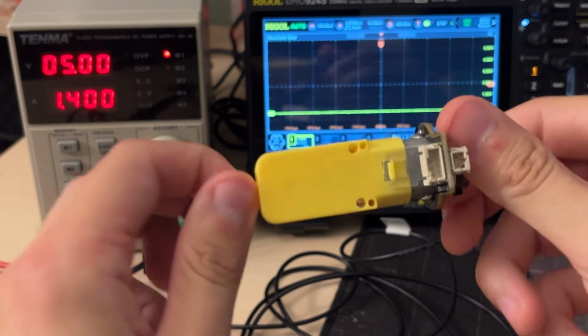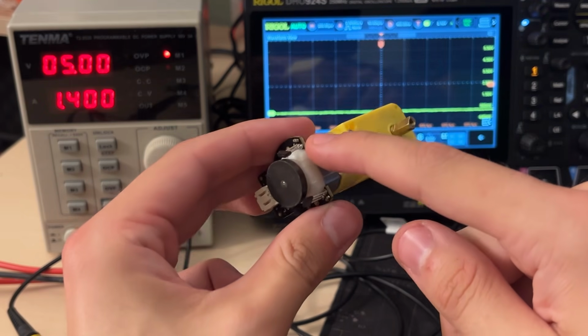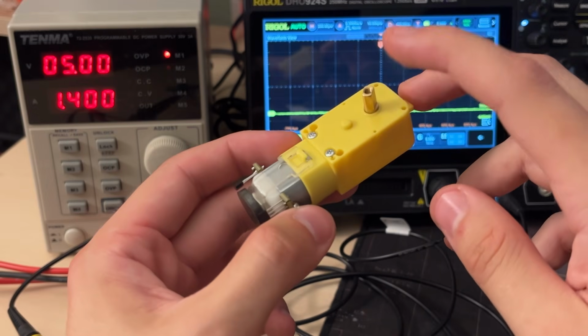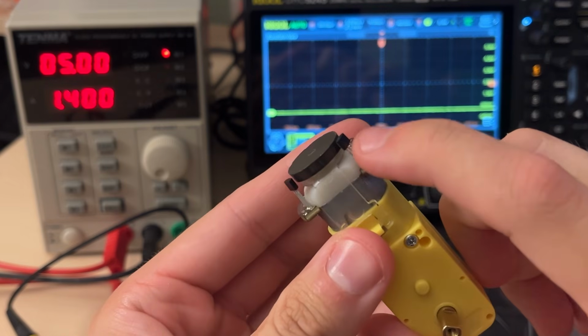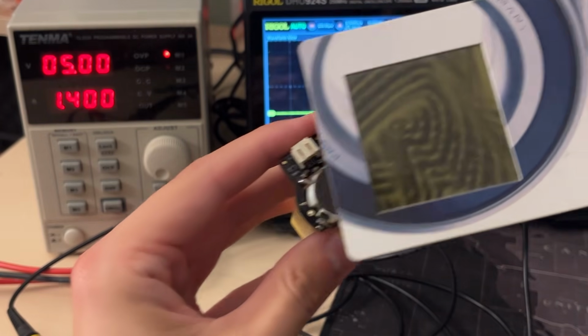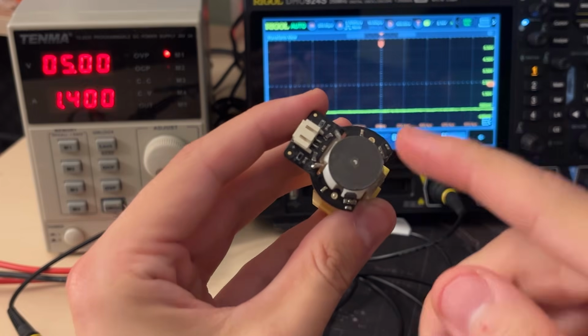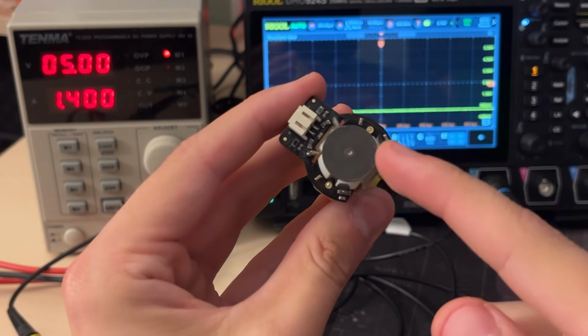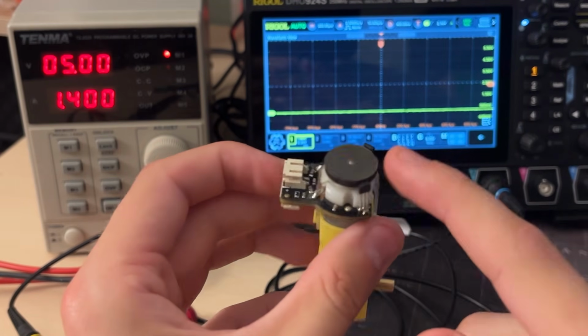First thing that we're gonna do is experiment with one of the motors that I'm gonna use that also has a built-in encoder and see what that's all about. Here is the key component for our robot, a small DFRobot actuator, and here's why it's so good. First of all, we have the small electric motor, then we have the gearbox, and here is the output shaft for the wheel, but also check this out. This here is an encoder. These two things here are small Hall effect sensors, and if we take a look with this magic little paper, you can see how this magnet looks, with a bunch of small magnets with different polarities, which can be detected by these two Hall effect sensors, which are put here at 90 degrees, and you will see why rather soon.